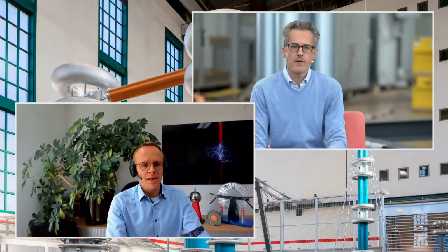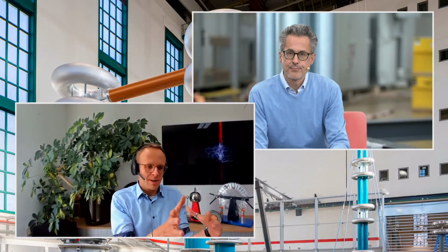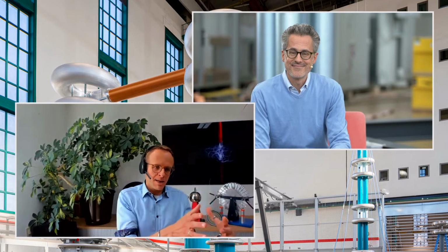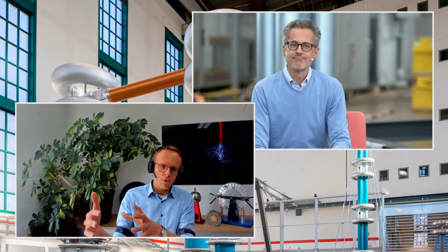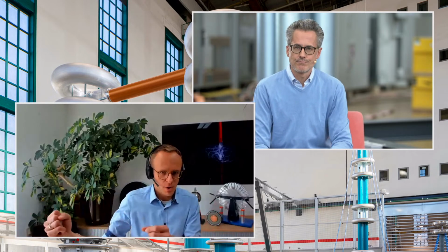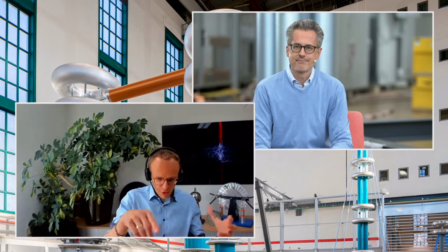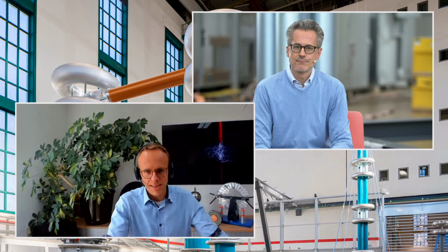Again, this is the part of universities, I think, to deliver the right way of modeling to the industry, so they can use the material parameters and the simulation tools to design their insulating systems. And then, of course, you also have to verify the models by maybe real measurements on original-sized mock-ups or so, to have a control loop closed for your simulation models.